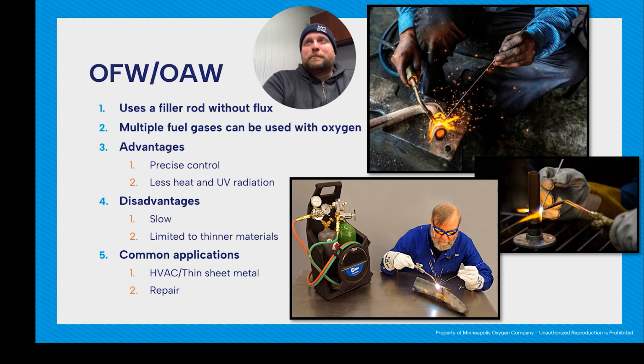So if we think about brazing something, you have two pieces, you're gluing them together, you still have two pieces of metal basically glued together, which is very simplistic, I know, but pretty accurate. But with welding, we take our two pieces of base metal and our filler, we melt them all together, now we have one piece of metal.